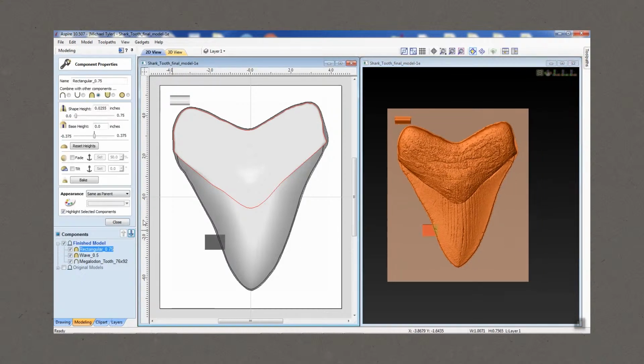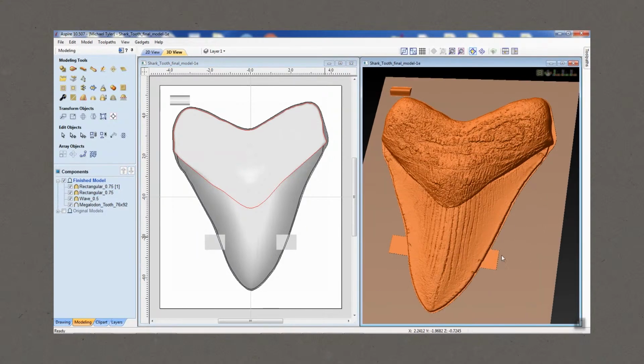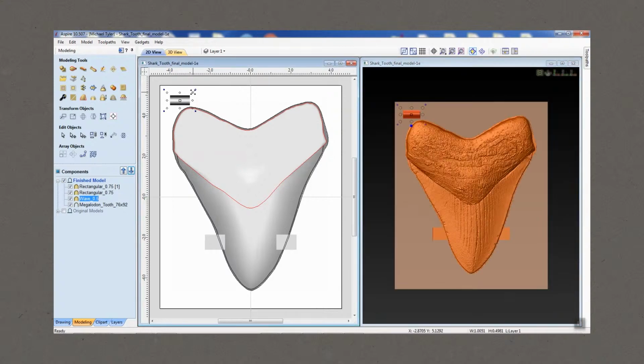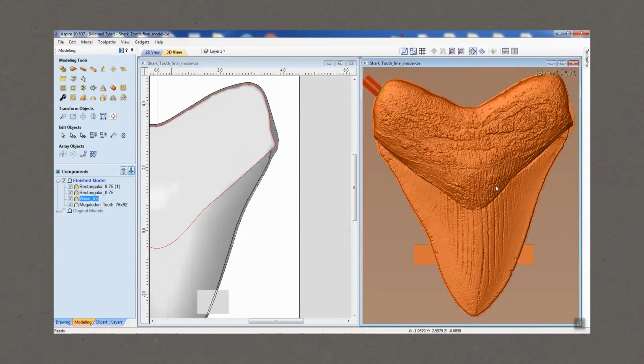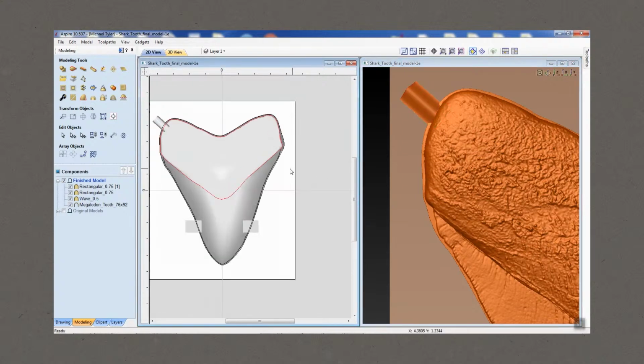And we'll just go ahead and click on this tab and press Control Shift H on the keyboard to make a copy to the other side. Okay, that looks good. And we'll do the same thing with this top tab. Now I'll go ahead and rotate this a little bit, and I'll place it on an area where it's not going to be too difficult to sand off after the carve is made. Now this one I don't care about it being flat with this bottom flange because it'll be easier to sand off anyway with this rounded fatter area. Okay, so I'll go ahead and select this, press Control Shift H, which makes a duplicate copy in horizontal.